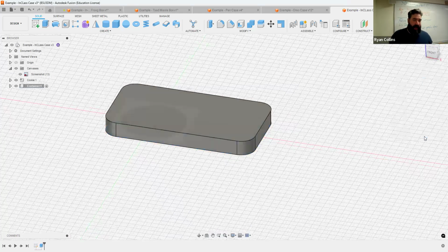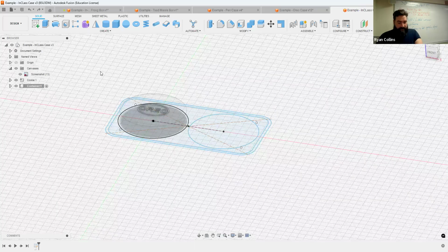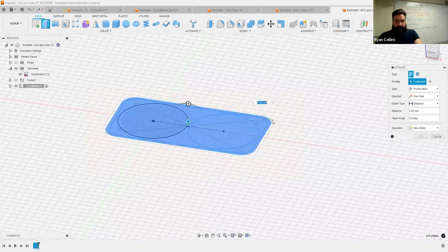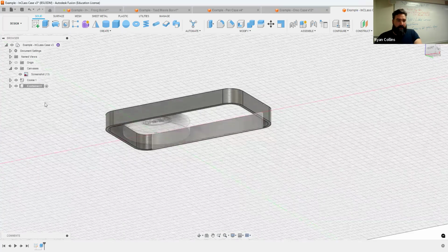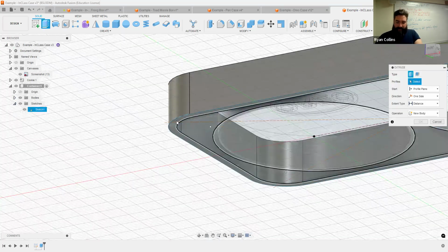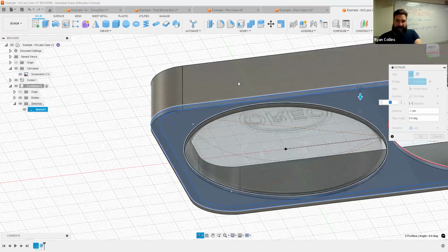Now, the problem is this is a solid block. What we could have done instead is do an extrude for just the wall. Let's drag that up the 10 millimeters that it is. Then I would need to add a bottom onto this. Unhide that because it automatically hides. So let's now extrude both that inside and that bottom, going down like -1. It doesn't need to be that much. Because the sketch includes several other things, we need to make sure we select both those circles as well.